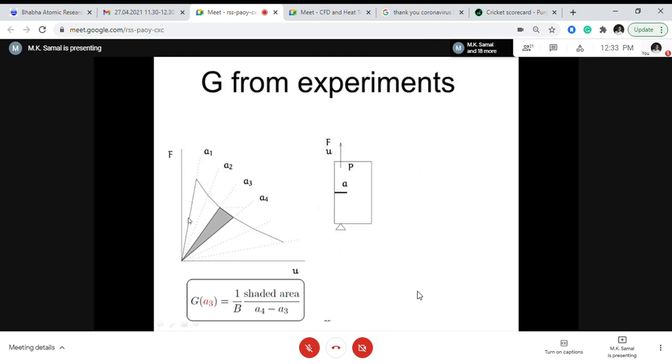Up to here it is linear elastic. Then after that, the load is reducing, the crack is increasing. So you are applying a displacement. You are just fixing it and pulling it by a certain displacement. As you go on increasing the displacement, the load goes on reducing. And when it goes to zero, the crack has propagated fully, and it becomes too fast. In case of load control, it will stop here, the displacement will go horizontally and become infinite. It will just break into two parts. So this is the difference for load control.